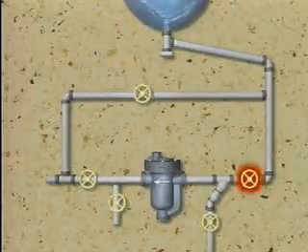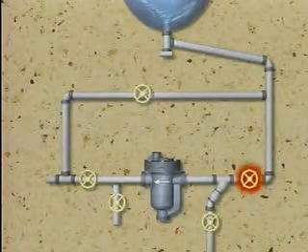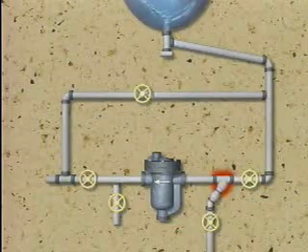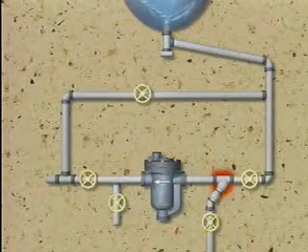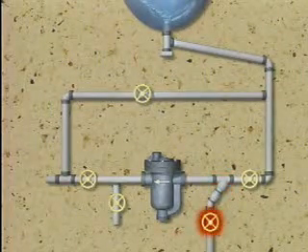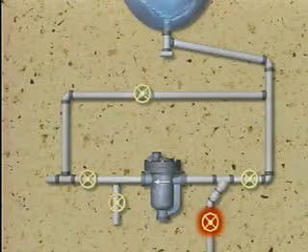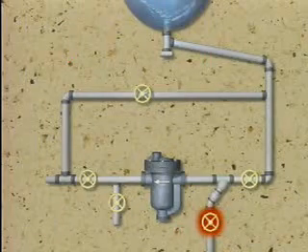An inlet valve isolates the steam trap inlet from the steam line. A strainer near the inlet valve prevents dirt and scale from entering the steam trap. A blowdown valve on the strainer can be opened to enable the strainer to be cleaned or blown down by directing flow back through the strainer to the atmosphere.